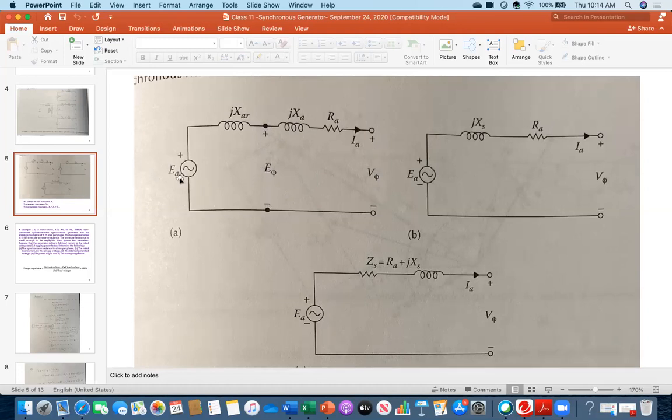And this one here means the internal generated voltage. So this is the highest voltage. Then it will have some lower value, and then further lower value because you have considered this drop. So based on this diagram, you have to find the air gap voltage, the voltage here. So you know this terminal voltage, which is given in the problem as 13.2.